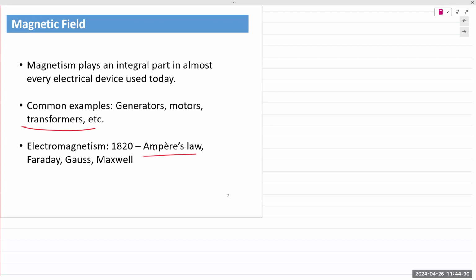The charger also has a coil. That also has a magnetic field. When you place it in close proximity, if it gets close enough, the magnetic fields link up. When they link up, the energy from the wireless charging base is transferred through the magnetic field into the magnetic field of your smartphone, which is then converted into electrical energy.